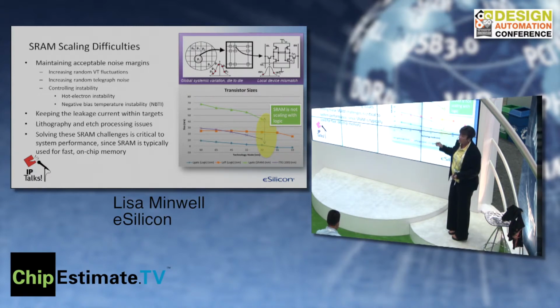On the lithography side of things, what we're seeing is that when you're dealing with coloring, for example, in an SRAM, if you think about a sense amplifier, you have to have devices that specifically match, okay? Very, very important. And so in our case, what we're noticing as we're looking through these technologies is that pre-coloring is a necessity.